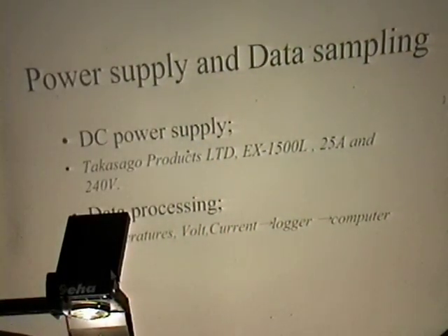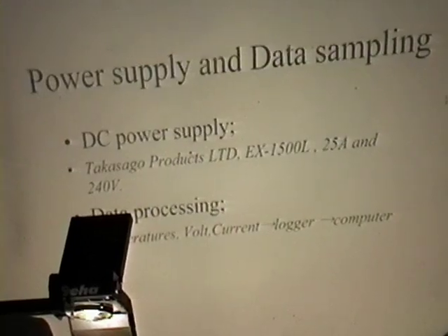All data, including voltage, current, temperature, and mass of secondary cooling water, are collected with a data logger every 10 seconds. Data from the logger is captured by the computer and finally recorded on diskette. The error of the input power and output heat can be estimated from the stability of the power supply, temperature, pressure, and flow rate fluctuation. This error is estimated as 0.84 watt.